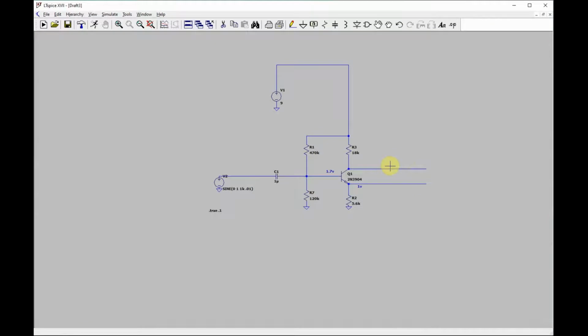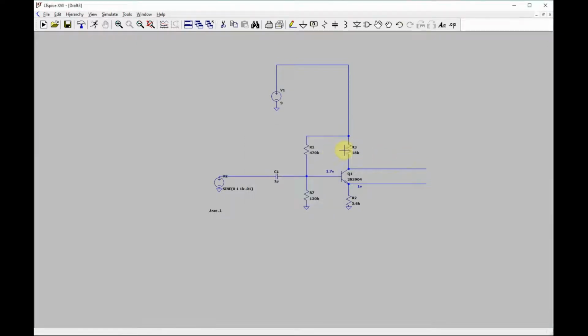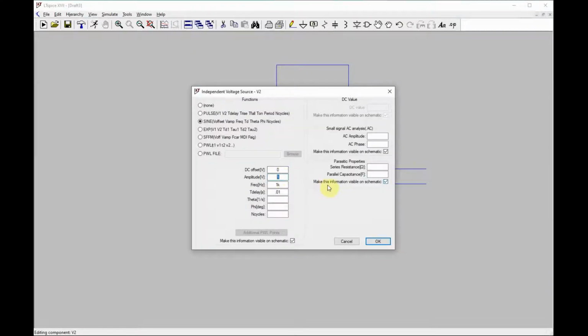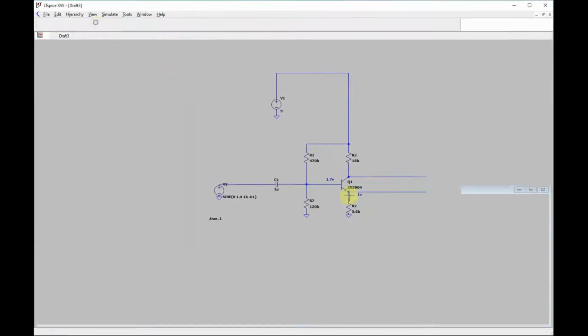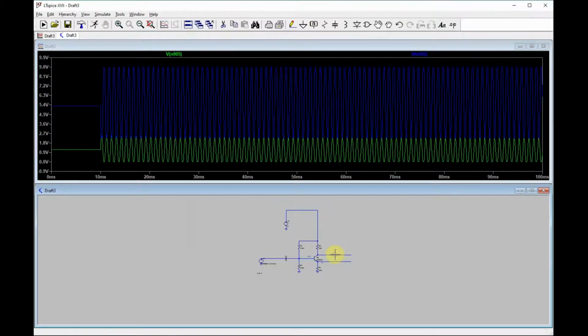Let's put a little bit hotter signal in, too hot, so we can watch it clip. Amplitude 1.4. Let's show you what's going on here. You've got these hitting and clipping. This is hitting the 9 volt clip. This is just clipping. You see, you just run out of room there.